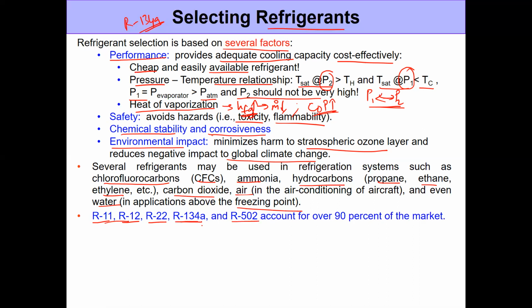So these are the ones which are capturing a lot of the market. When we talk about the industrial and heavy commercial sectors, they tend to use ammonia because they can have the maintenance and the safety protocols followed very strictly, which you cannot always do, especially the maintenance protocols cannot be done at home. So they can use ammonia for getting better COPs. We really can't do that. And that's why these above refrigerants, which I mentioned, are the ones that have captured the majority of the market.